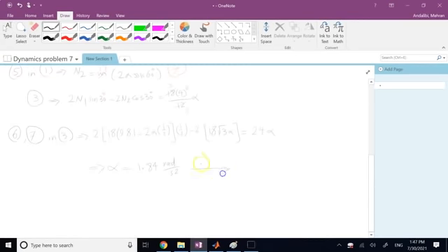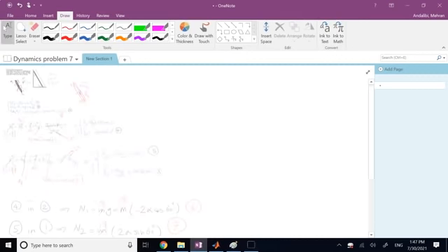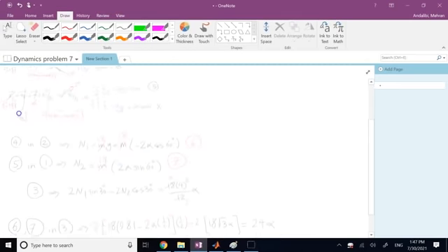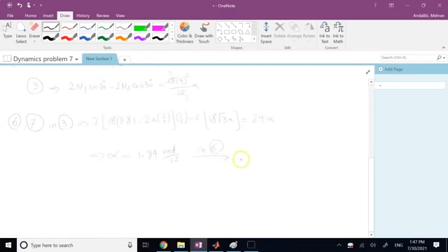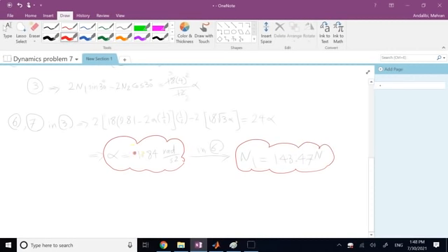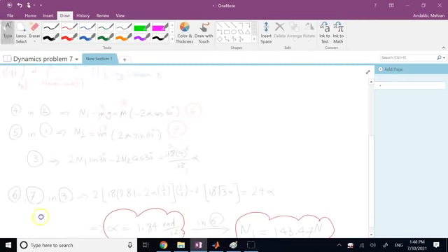6, so if you plug it in 6, it can give you n, well, I need n1, yes, the one from the floor, and that is 6. So n1 is going to be 143.47 Newton. Okay, so these are my solutions: the angular acceleration at the moment and the force coming from the floor. And if you plug that alpha into 7, that gives you the force from the wall.